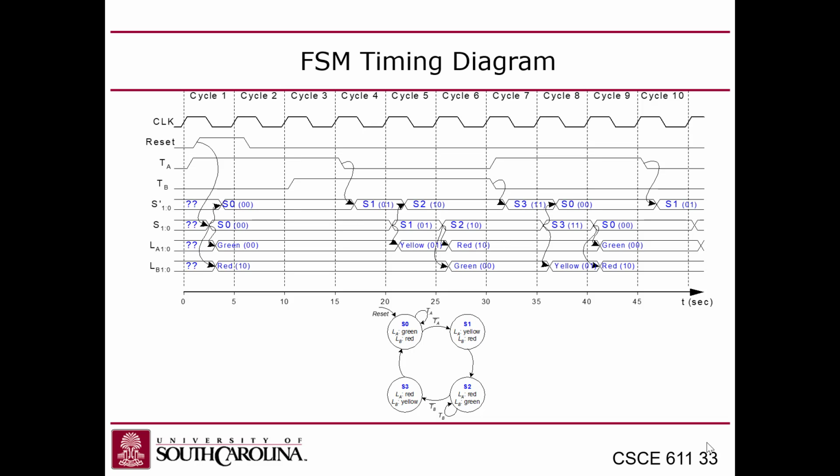Now, another thing about this timing diagram that's a little confusing is that in Model Sim, a lot of these things will be happening at the same time because, as I mentioned last lecture, there's no propagation delay in Model Sim. So when there's a rising clock edge here and a transition that happens in response to that clock edge, notice how that clock edge rises right in the middle of that dotted line there, right? But the change in state, you see they put a little bit of a delay there? So they don't change state right on the dotted line.